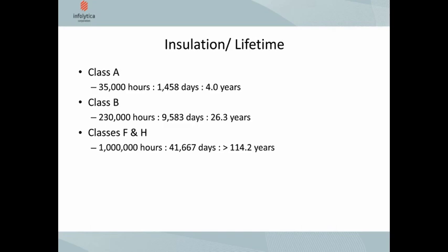If your warranty is instead 25 years or 10 years or something in between, you definitely would need to jump up to Class B. And if you needed to ensure a permanent lifetime of the motor, you'd have to jump up to Class F and H. But knowing the temperature of the winding ahead of time allows you to make a cost-benefit assessment of what sort of insulation you need to put in.